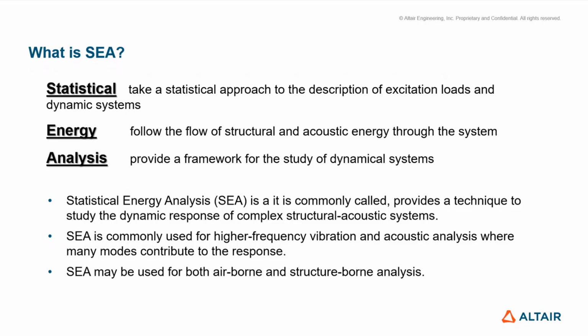So that is the main solver behind the scenes. Because of this statistical energy analysis, as it doesn't need any nodal information and it needs energy information, it can be used up to high frequencies also. And it has the capability to solve both airborne and structure-borne analysis.